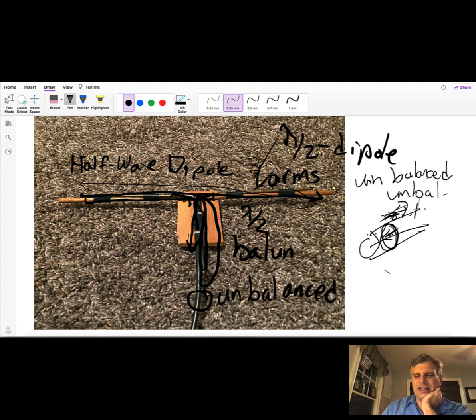on the outside of the transmission line, which means instead of just having a standing wave of current with a nice sinusoidal taper like we've discussed in our half-wave dipole, you get a lot of extra current flowing on the transmission line itself on the outside that contributes to radiation. This messes up the impedance of your antenna, how it behaves in a circuit, and it also messes up the radiation pattern and all the things that you were trying to do in a simple antenna.